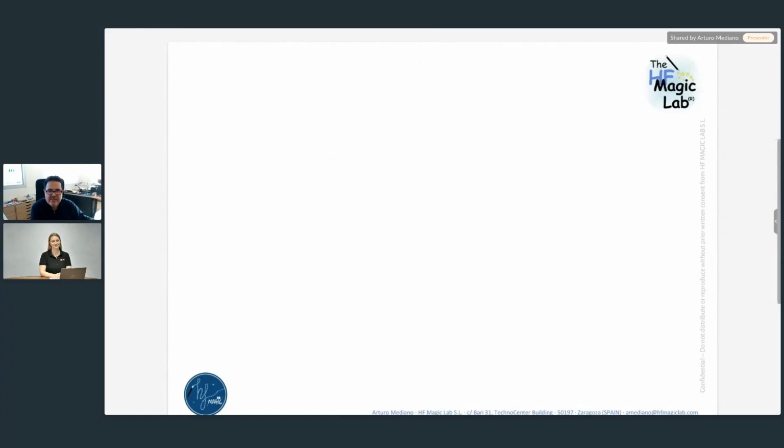Yes, I think common mode chokes are good components to increase the immunity of systems. Of course, in my opinion, both common mode chokes and ferrites. I have read some time ago many people writing in social networks or on websites that ferrites are dangerous or common mode chokes are not so useful. In my opinion, they are very good components, like capacitors or any other component. The only thing is you need to work with them correctly. You need to understand the data sheet, the limitations, where the saturation is, what you are introducing, inductance or resistive effects. But common mode chokes are a really interesting solution to minimize both emissions and immunity problems for sure.